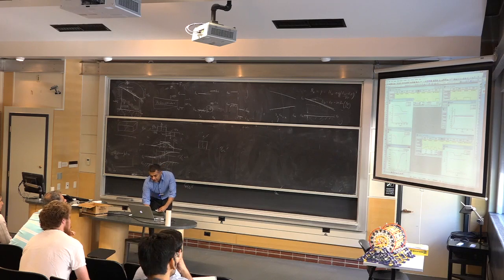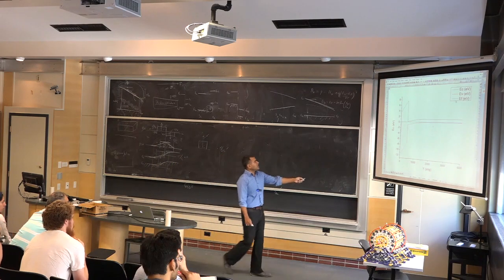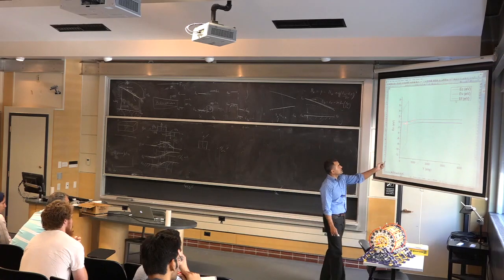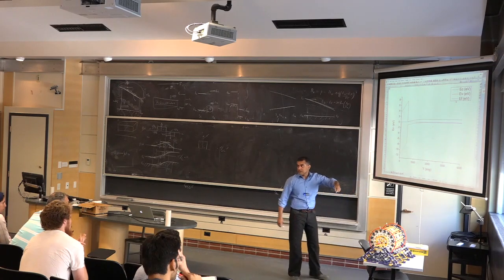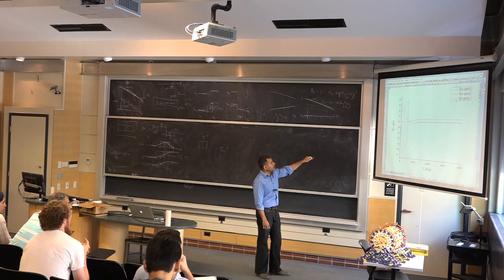So, yeah. For example, if you take a diode, which is a metal insulator semiconductor structure, so you have metal, silicon dioxide, silicon. It's a MOSFET, MOS structure. Right? So it will calculate your energy band diagram. And here's the very wide band gap silicon dioxide. It's an insulator. Here's silicon, 1.1 eV band gap. And you have applied 4 volts on the gate metal. And the bands are bent.